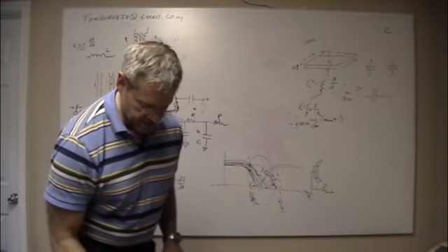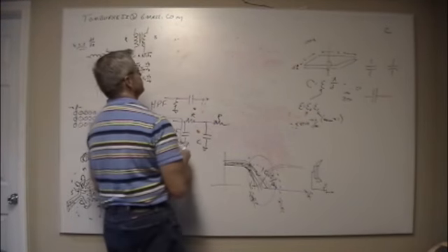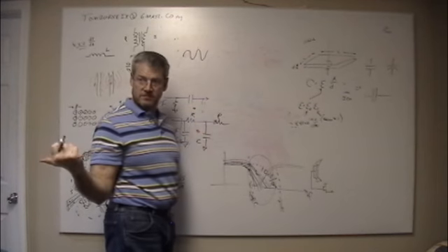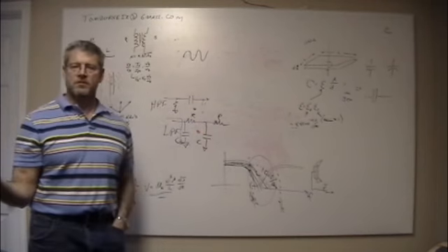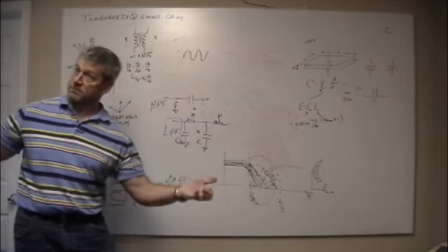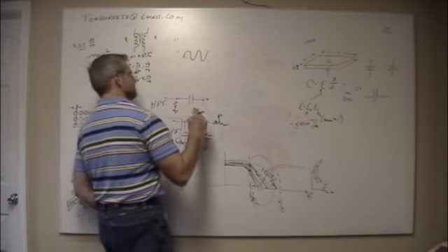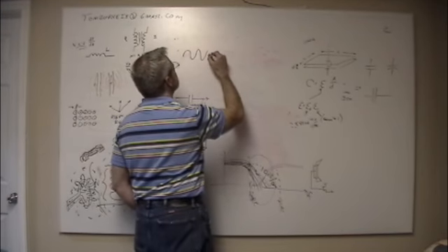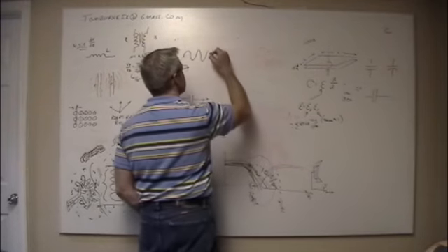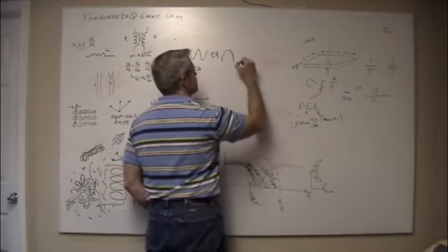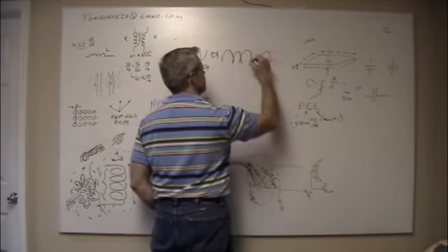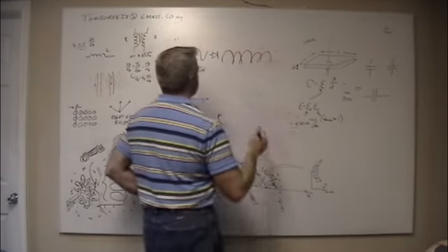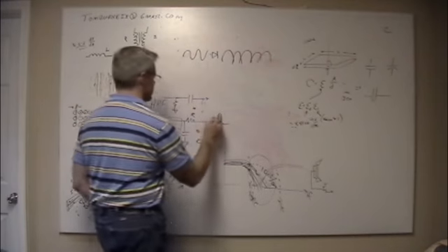power supply design. We talked about before, you take your power off the wall as a 60 cycle, 60 hertz. That hum is 60 hertz, about there, right? Give or take. What you do is you go through, on a really old system, it'd be a half-wave rectifier, and you get this. If it's a full-wave rectifier, you get this. So actually, you're probably hearing 120 hertz. And so you do this game right here.